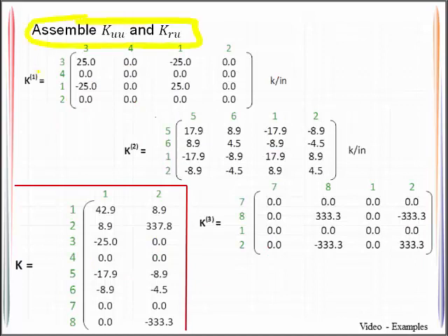What we would do is take the element stiffness matrices, all 3 of them here, and we would simply identify the terms that have the same subscripts. So for example, if I wanted to find the K31 term in my global stiffness, I would scan all of my element stiffness matrices for a K31 term. I've got a term there, but in element 2 and 3 I don't have that. Let's look at another one.